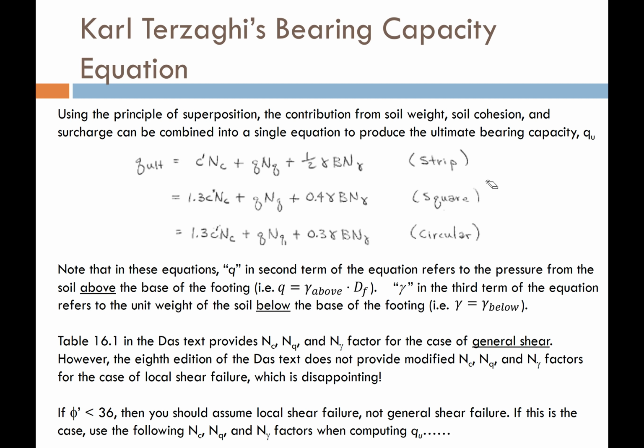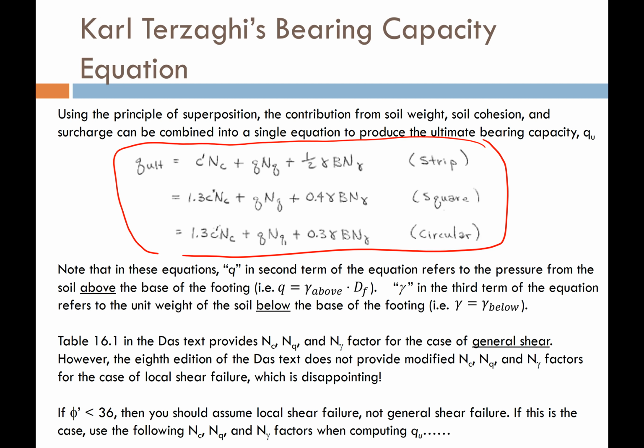They've developed relationships for bearing capacity of stiff soils over soft soils and soft soils over stiff soils. And so you have multi-layer solutions, and there's all sorts of stuff out there. These are just very simple equations for a uniform soil layer beneath different footing shapes.